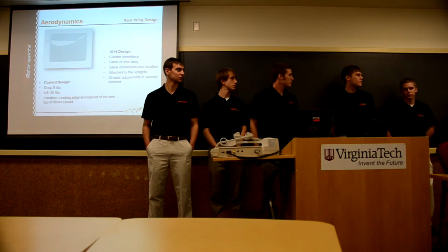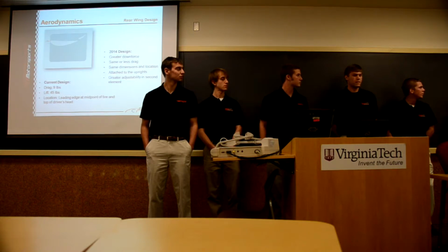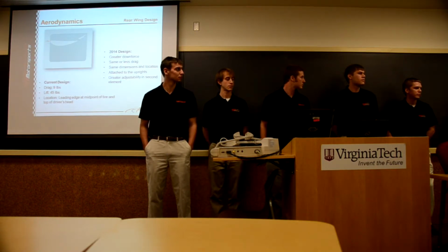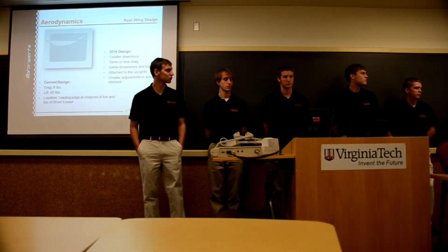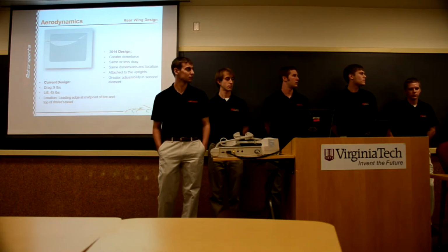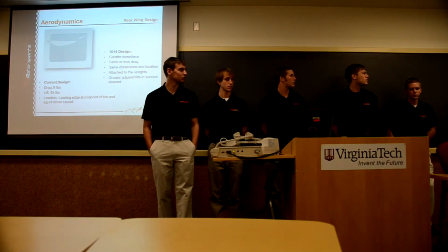For the rear wing, right now, we're looking at about 45 pounds of downforce and 9 pounds of drag. We actually have one more CFD test to run with this same wing profile at an increased angle of attack, so we'll be looking at more downforce and also more drag.